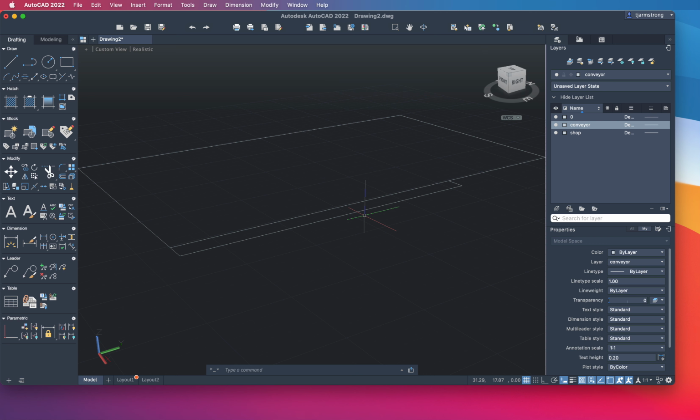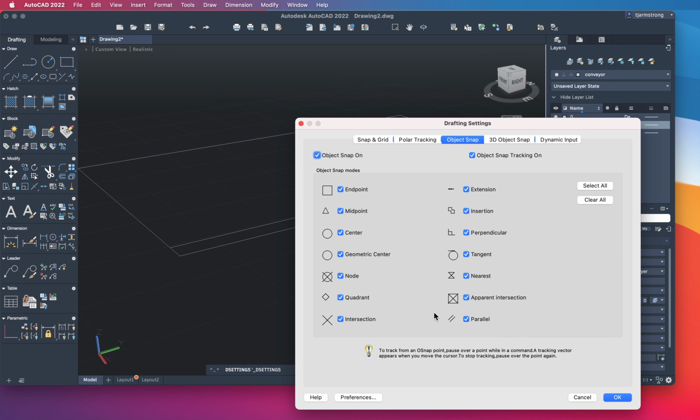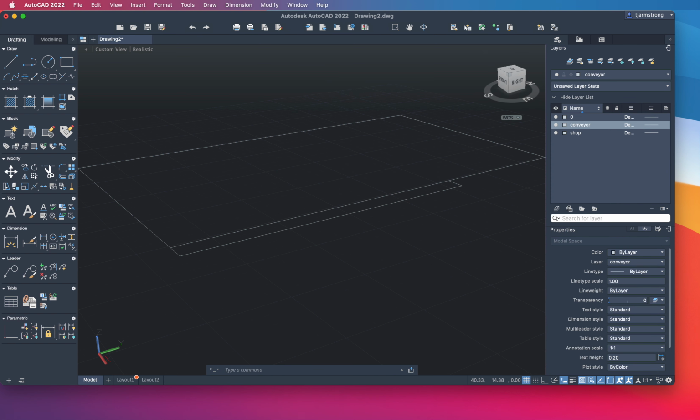I can put it anywhere. I just linked it to this corner, because the next thing I'm going to do is move it to the center of the workplace. Now, you might want to check your snap settings, because this is going to affect how easy it is to do this next one. So I'll go over here to Object Snap, and I basically got everything turned on. You may or may not want to do that in some cases, because sometimes you'll have too many snap things close to each other, and they'll interfere with each other. But for now, let's just go ahead and try it.